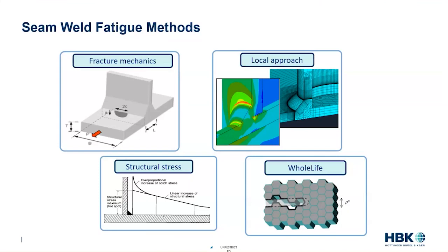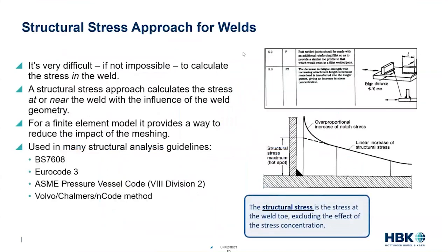So when we talk about structural stresses, they are a technique for us to recover stresses that we could use in a damage calculation, but have certain properties. One, it's virtually impossible to get the actual stresses in the weld. Like I said, the weld geometry is extremely complex. There may even be existing cracks in there. So the actual calculation of the stress in the weld, measurement or physical in an FE solution, is pretty much impossible. A structural stress is looking at, in essence, the load going into the weld.